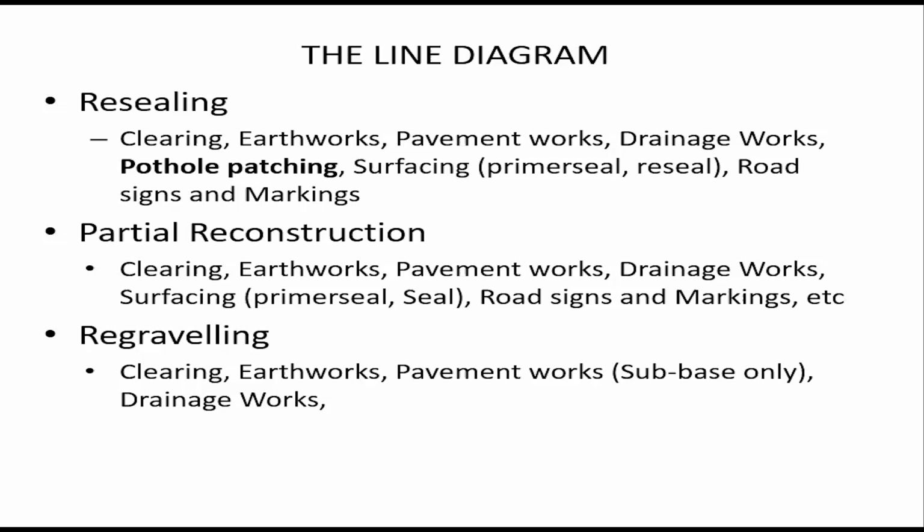Then we have partial reconstruction, which is also having these activities: clearing, earthworks, pavement works, drainage works, surfacing, of course, primer seal and seal, road signs and marking. As for partial reconstruction, you don't touch the alignment of the road. It's virtually the same alignment that you use. So at the end of the day, the road is still the same by way of alignment. That is why they say partial reconstruction.